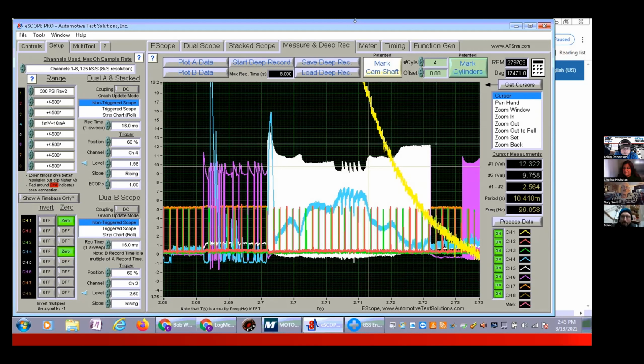Yeah. The neat thing is this test that we're doing on this screen is, unless you are a student of some more advanced thought process with testing, you're not going to catch this because your current probe is around one of the phase wires, not all three, and you're not looking at Kirchhoff's current law to catch that. Exactly. Right. So that's the beauty of us getting together and sharing these testing ideas. Like, for example, why can't BMW say, use Kirchhoff's current law, put a clamp around all three and look for leakage?